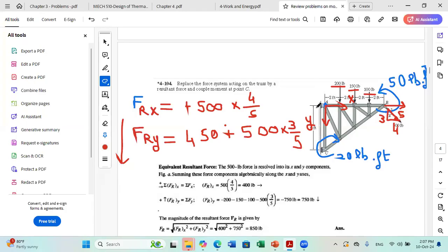When I say moment, I want to reduce at A, I should do the sum of moments about A. Because when I move a force to A, I should add its moment about A. I should consider the moment it's producing about A. And don't forget, I consider moments of forces and I consider couples. We have seen together that the moment is a free vector.